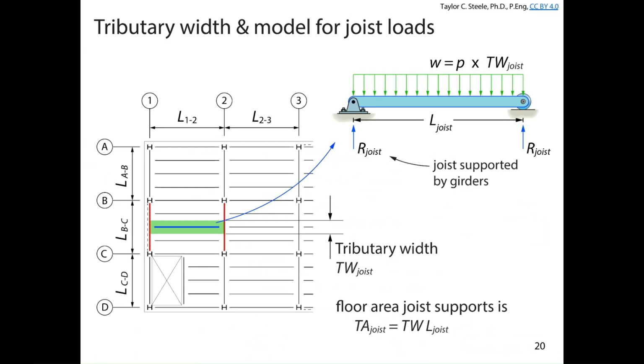So moving on with that, we're going to start with tracing the loads from the floor down through the joists into the girders and into the columns. Okay, we build a structure from the columns up to the joists to support the loads from the joists down through the columns. So the first element that's responsible for supporting, for example, somebody standing on the floor is the floor itself, but the next element down is the actual beam. In this case, I'd expect that on the top right-hand corner here, everyone knows how to draw the shear force and bending moment diagrams for a joist.